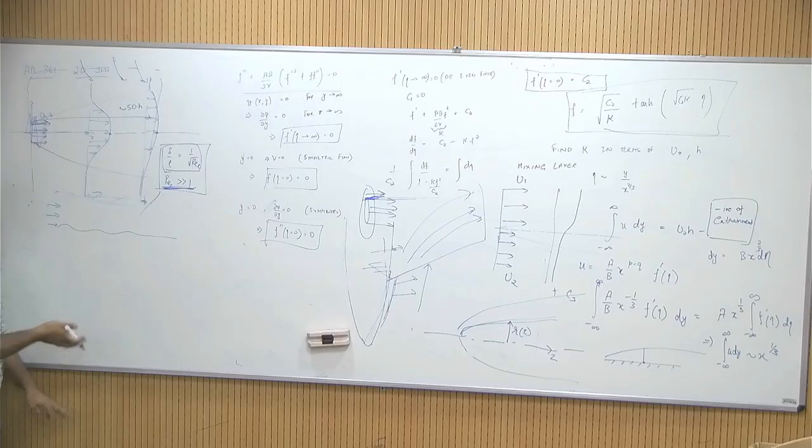Even on a flat plate, when you have just a plate and you have a flow u infinity, if you just look at the inviscid solution, you don't get a drag, but we know there is a drag force that is exerted on this plate. So the practical use of all of this is eventually to calculate what is known as the skin friction drag.